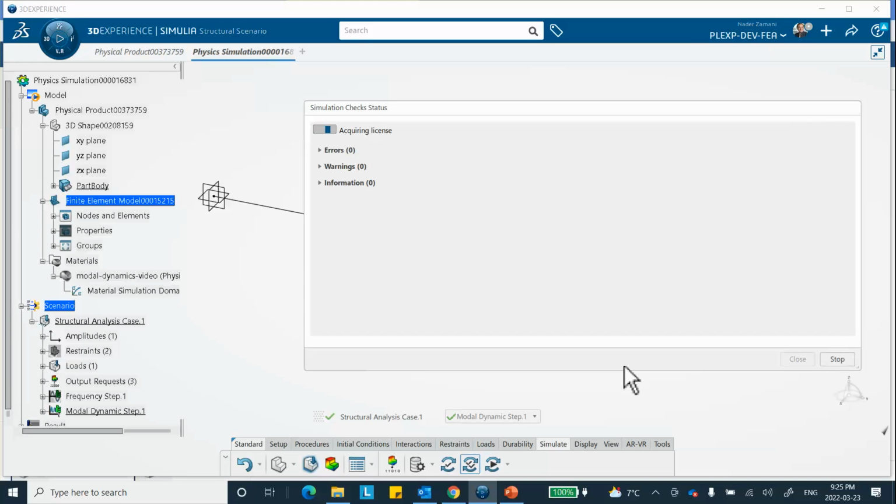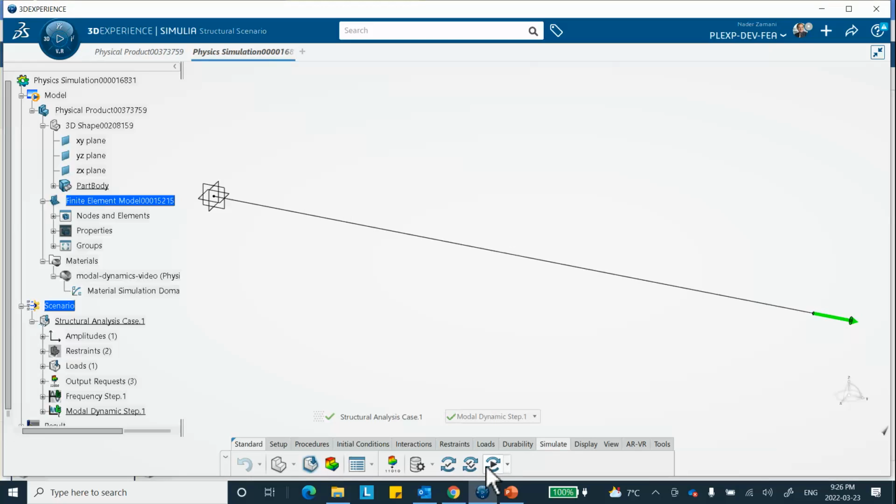So if you want to plot the stresses, displacements, and things like that, with the color codes that you're used to in finite element, you have to ask for a field output, not history output. Okay, this is done. And this was the simulation check, and now we're going to run it. This is the actual moment of truth, whether it's going to run and create the graph that we want or not. We'll see.